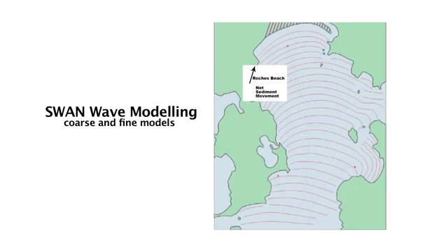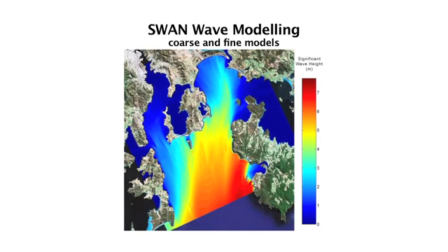So some examples of the more complex method. This is a proper, what we call SWAN wave modelling, where in this particular case we could have waves of between 8 and 10 metres out in the deep ocean out here, and the swell lines, this is like wave crests, and they propagate up into a bay like here. And obviously they're much smaller up here than they are out in the deep ocean. This is when we run that through a computer model. In this example, the model's SWAN.